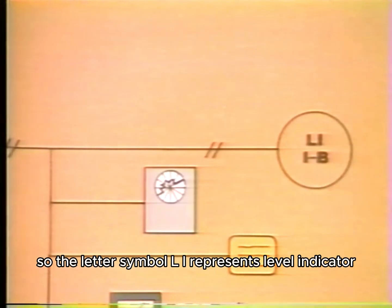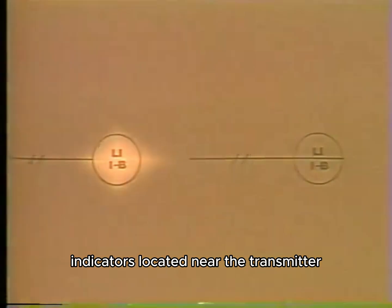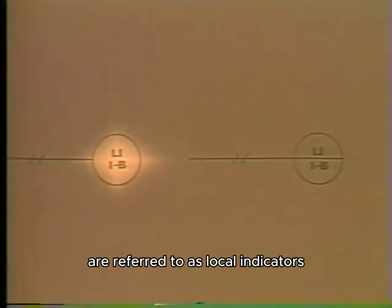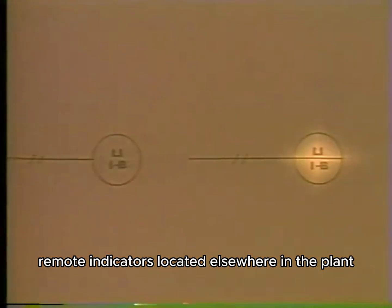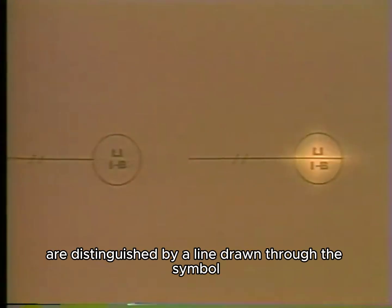So the letter symbol LI represents level indicator. As we stated earlier, indicators located near the transmitter are referred to as local indicators. Remote indicators, located elsewhere in the plant, are distinguished by a line drawn through the symbol.